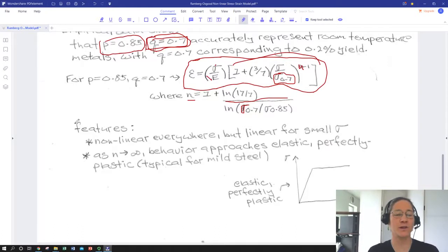Granted, it does come with a price in fracture toughness reduction, but knowing how much additional stress we get for each increment of strain in that plastic regime is part of what this model is giving us, and it's contained within that N. So we can use that relationship and some given test data to get at least a general idea of what's going on in the plastic region.